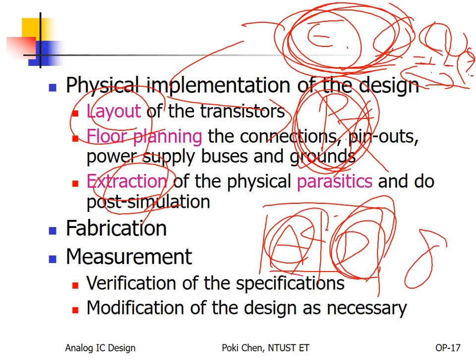Even a flip-flop, usually the traditional static one, has more than 8 transistors. How about your op amp? Less than 8. Again, the op amp and most of the analog devices dominate the accuracy of your circuit, but in number they are much fewer than the digital part. For simulation, your SPICE is not so smart. It treats one transistor, never mind digital or analog, the same. It spends the same effort to simulate your digital transistor and your analog transistor. That doesn't make any sense because it wastes a lot of time.